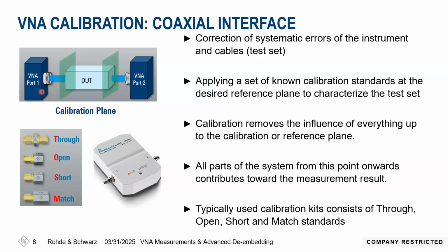Then when we connect these known standards at the end of our cable, from which we usually connect our components, and we perform the calibration, the VNA internally calculates with the known data of these standards, and all the effects of the internal components and the cables are removed.